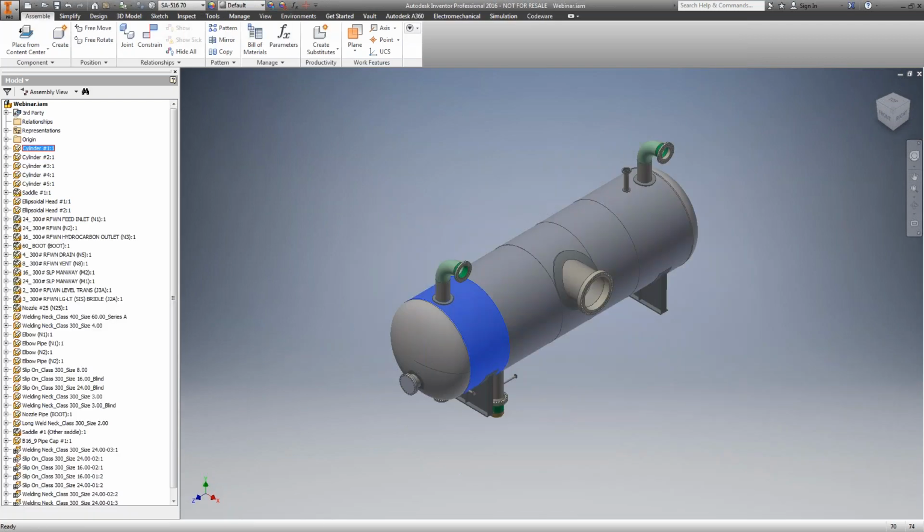So that's going to be available to you as well, but more importantly are the properties. Now I try to stress this a lot because they're so valuable. I see hundreds of drawings come across my desk every year, and I'm noticing a trend where a lot of the information is going to be tabulated in tables. So if you right click on any of these components or the assembly itself up here, you can select this option here that's called iProperties.